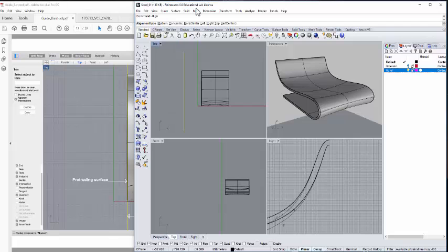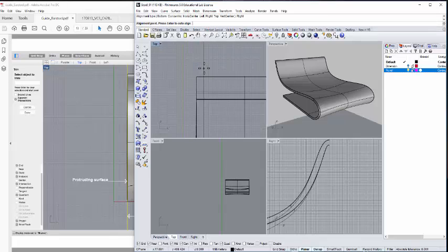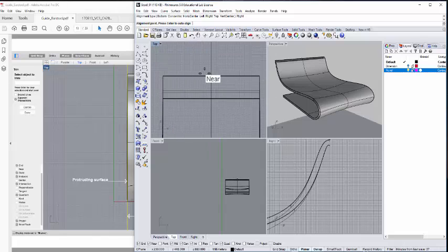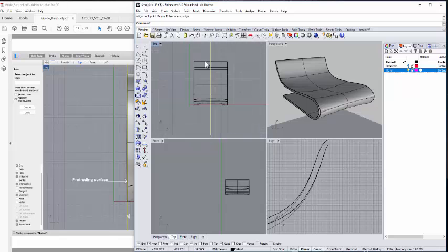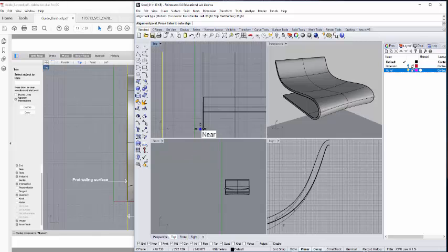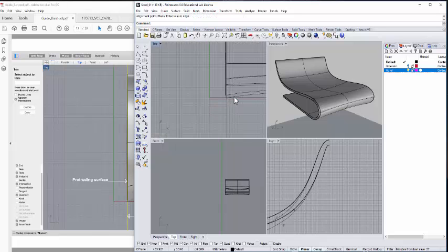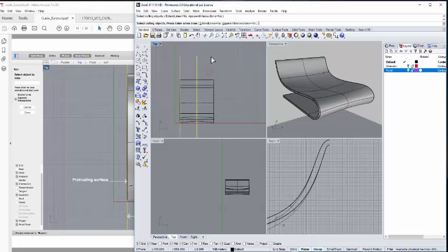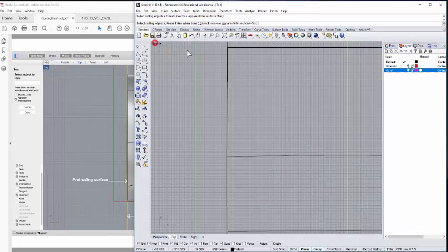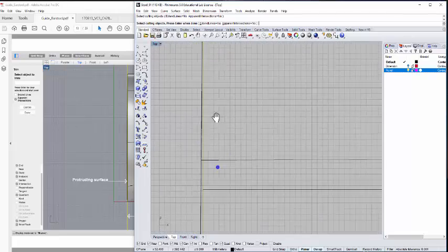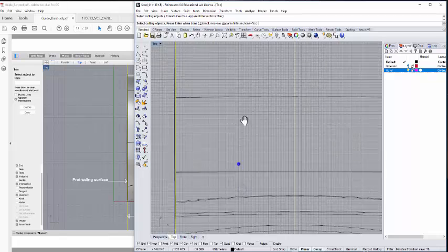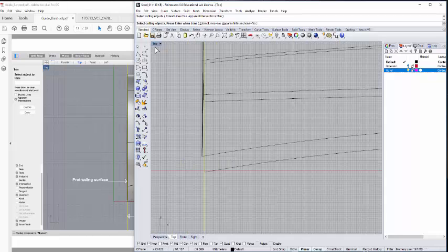and then I will use a line, and then I will move the line, snap to the right, and then snap to the center here. Okay, the other line I will snap again, right, and then let me find an edge to snap. Okay, let's snap here. Okay, next I need to start to trim. These two will be my cutting objects, so just double check. Make sure you get the right line.